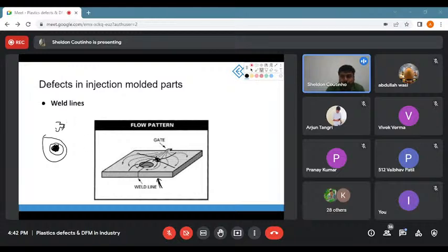Now that is the point where your gate was connected to your plastic component where it was broken after the component was formed. This is something that is not avoidable. ये avoid नहीं कर सकते, parting line avoid नहीं कर सकते. No matter how hard you try, you can never avoid a parting line. Then let's come to Vaibhav's answer. So Vaibhav's answer was let's reposition the gate to this part.